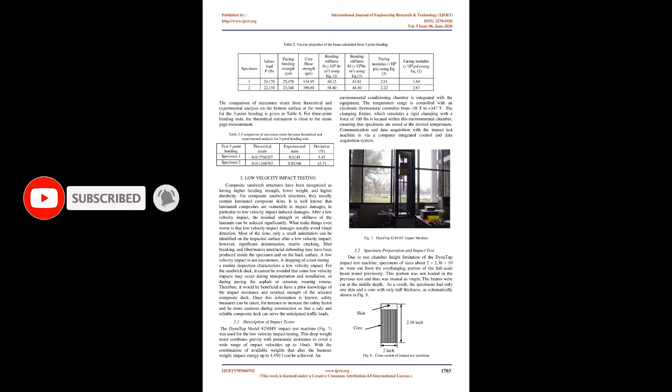2. Flexural testing. 2.1 Test fixtures and instrumentation. Fig 1 shows 5 beams with strain gauge and Fig 2 shows the schematic view of the test fixtures and other instruments used in the 3-point bending test. Load is applied using a universal testing machine, Forney, from the bottom of the specimen. 1 fixture is used for 3-point bending test. The bottom fixture is supported by the Forney machine load plate and the upper fixture is restrained by the upper fixed frame of the machine.